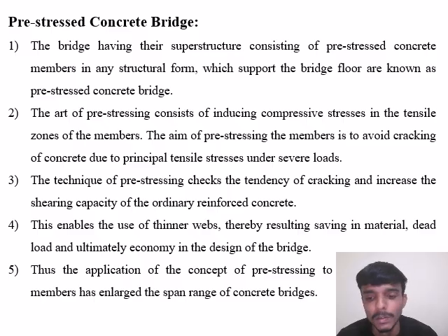In these bridges, the pre-stressing method is used, in which the inner reinforcement is in the form of cables which are stressed before concreting, and the concreting is done while the cables kept as reinforcement are already stretched, after which they are released when the concrete is at a rigid state.